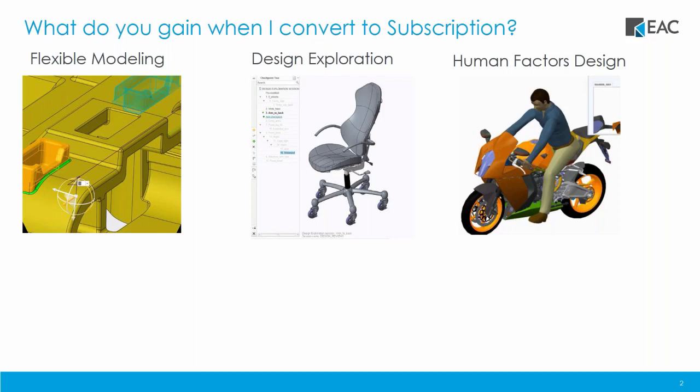A little bit on flexible modeling. What it does is it makes design changes a lot easier to do. You are allowed to create Creo data changes regardless of design intent. So you can modify non-Creo data regardless of its origin, whether it's STEP, SolidWorks, CATIA, NX, that kind of thing. You can recognize rounds, chamfers, patterns, and create or recreate design intent and record edits as features. So that's one of the benefits with flexible modeling.